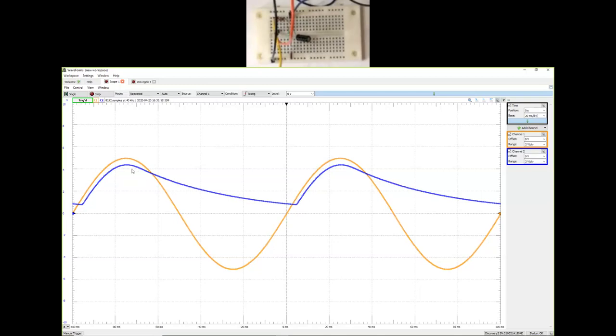So now that we have changed it to 10 hertz, we are allowing that capacitor to discharge for a longer time. And in fact, you can see that this is looking more and more like an exponential decay. Earlier, we were looking at it as almost a linear decay because the points were pretty close to each other. Now that we are extending that time, we are able to see that it's an exponential discharge. So the ripple voltage over here is very pronounced. It's pretty big. So this is not a very good way to convert an AC to DC.